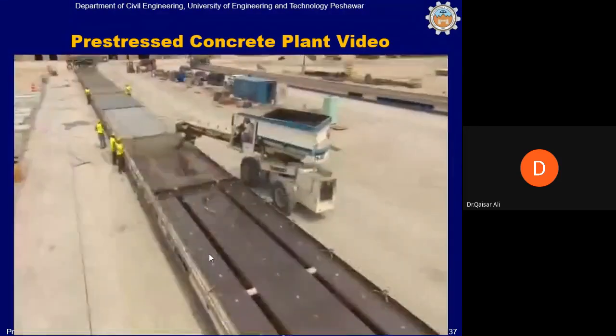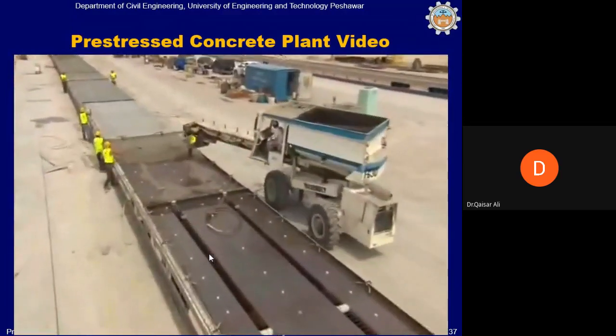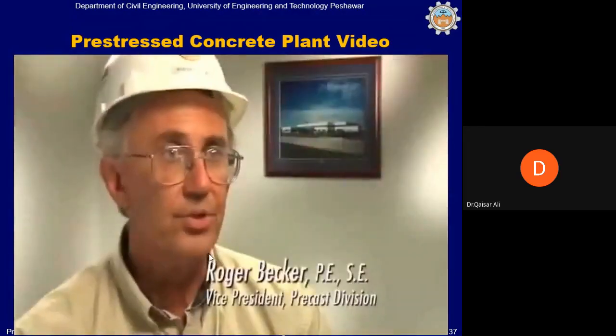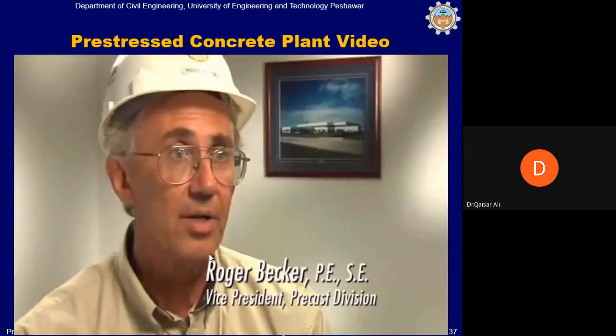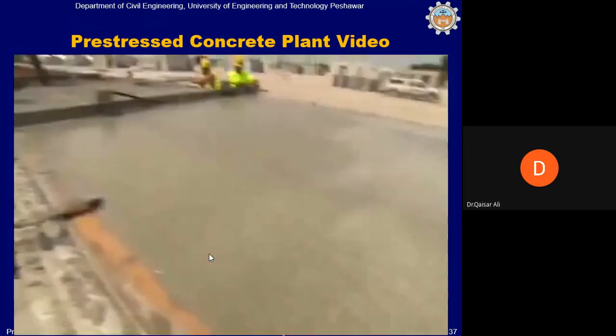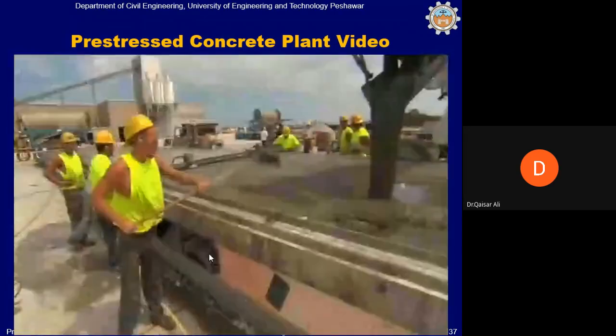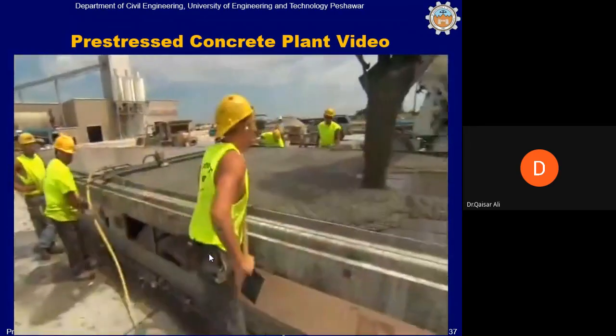There are many advantages in using this type of concrete. We do use self-consolidating concrete for our double T's. We feel that it gives us a better finish. We feel that it's easier to place, takes less labor, less strain on labor to place that concrete.